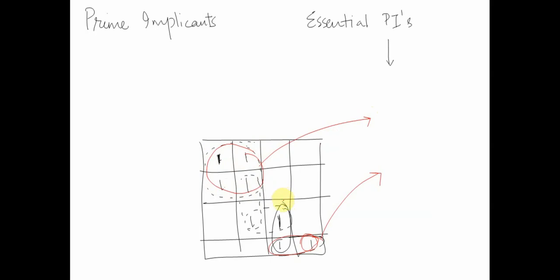So prime implicants are the largest groups present in the entire K-map. We saw that we had 1, 2, 3, 4, 5 prime implicants. Essential prime implicants are the ones comprising terms which occur only once, and those groups are essential for the appearance of this particular term, right? Let's put numbers to the essential prime implicants we spoke about.